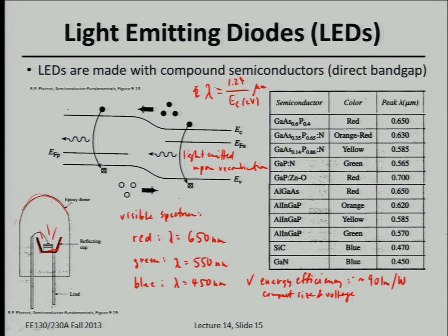Remember, the built-in potential for a PN junction diode is less than, but comparable to, the band gap energy. You have to reduce that potential barrier to let significant current flow. So the larger the band gap, the more voltage you need to apply to have significant light coming out.